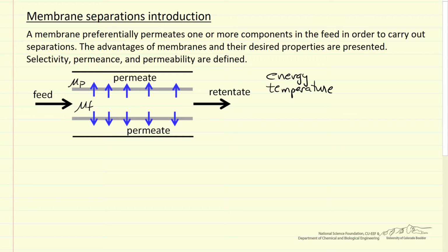If we're not evaporating, not heating to a high enough temperature to get a significant rate of evaporation, then materials that are temperature sensitive are not going to be damaged. Also, if we have a mixture that possesses an azeotrope, which makes separation by distillation difficult, this is not going to be important for membrane separations because we're using a different mechanism. Likewise, if two components have boiling points close together, requiring a very large distillation tower, membranes using a different mechanism can separate such a mixture.